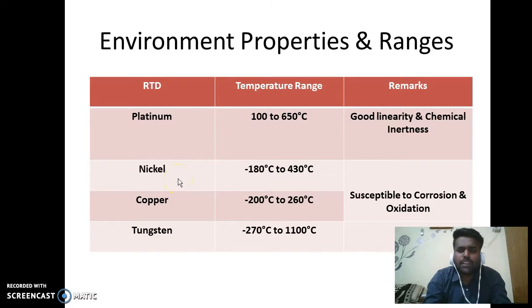But if we look at a particular application like air conditioning systems, the RTD temperature sensor mostly uses nickel as the metallic resistance, because it is abundant in nature and very cheap. Nobody is going to check the accurate temperature when setting it through the remote of an air conditioner. Nobody is going to sense it. So in those cases, the manufacturer gets a benefit from using these metals.